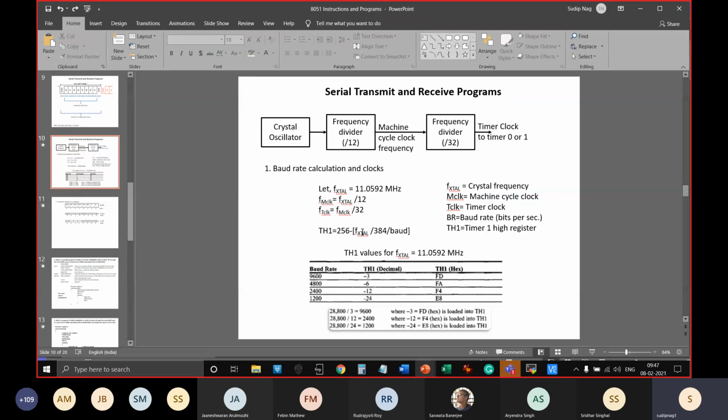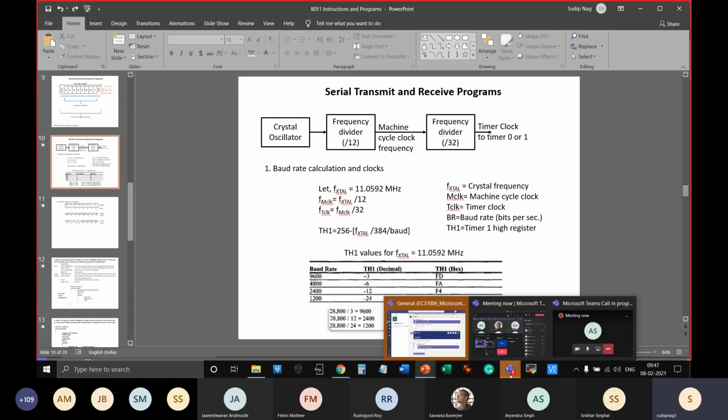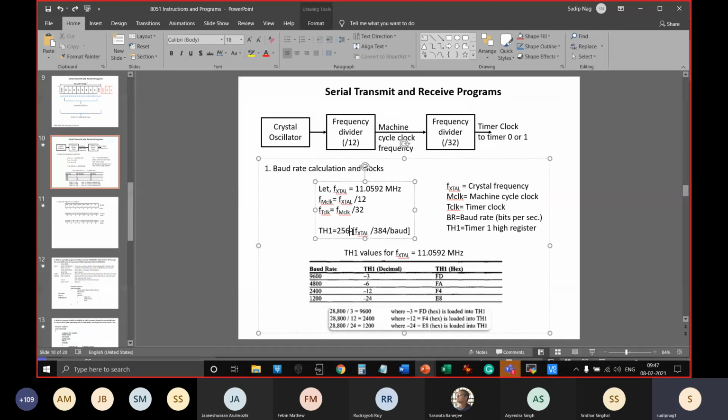You can work out with certain values and check this out. In every microcontroller, it is actually minus only, because most of them have minus. In UART communication there are certain timer modes reserved for serial communication, and there it mostly does minus. But in ARM7 or some other ARM variants, you will find both up and down counting available from the timer. For serial, it is typically any one of these two, which is reserved particularly. So in 8051, it is only down counting which is available in auto reload.